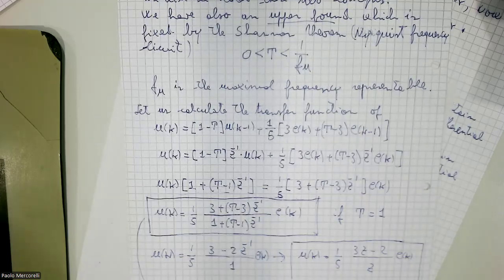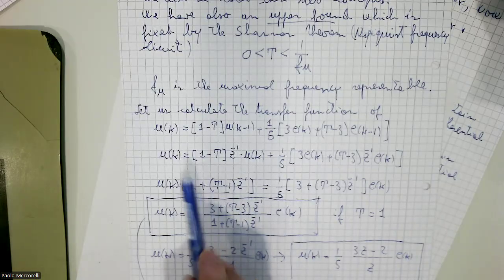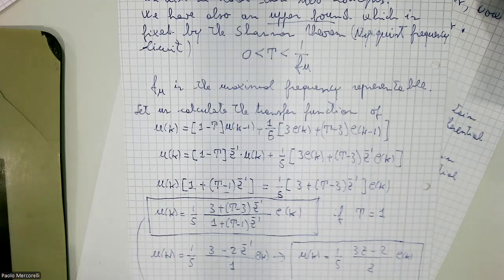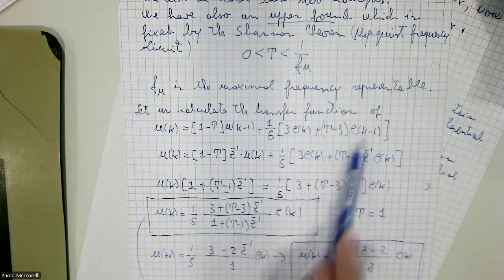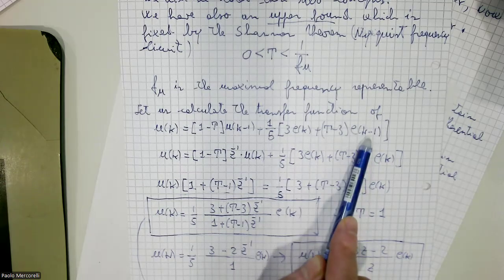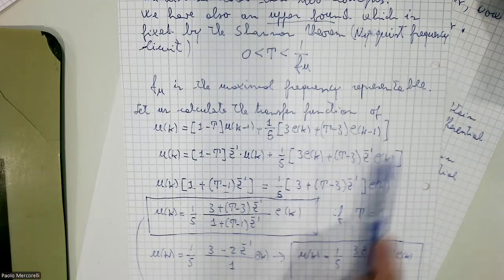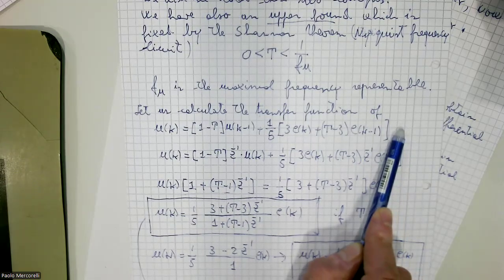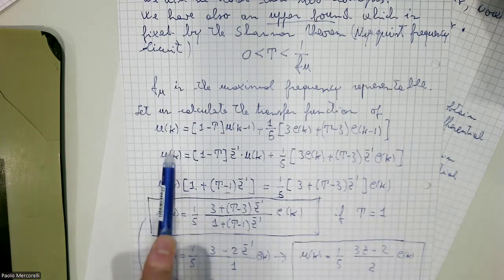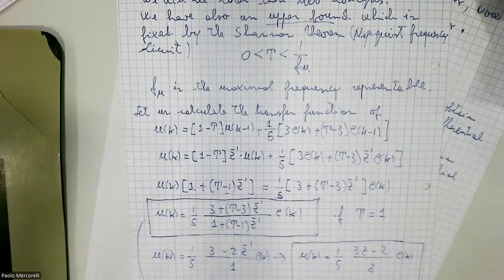I can save it in memory. In Simulink, with the memory, with 1 divided by z, it's easy to understand. We have never tried the same notation, but it's clear that 1 divided by z is in the memory. This means shift. I have to build a buffer. How long? In this case, 1 element, because this is the actual element and this is the past one. Just one step. But if I have somewhere E of k plus 1, this is the problem, because the output of the controller depends on the future input. But we don't have it.